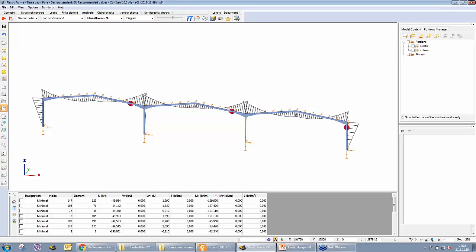There was earlier another webinar fully on this topic. It was just a brief summary of the capability and the results, and I wanted to stress the difference between the first order and second order plastic hinge analysis, because usually when we use plastic analysis, the strategy is that we would like to see as slender elements as we could, and then out of plane we use a lot of points to stabilize the out of plane buckling, but in plane we usually do not have any chance for stabilization.